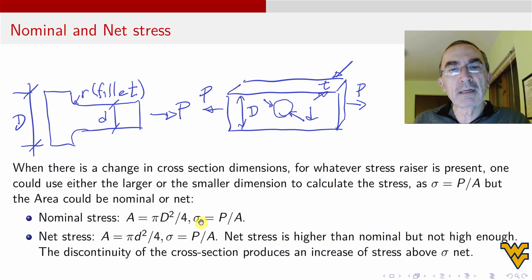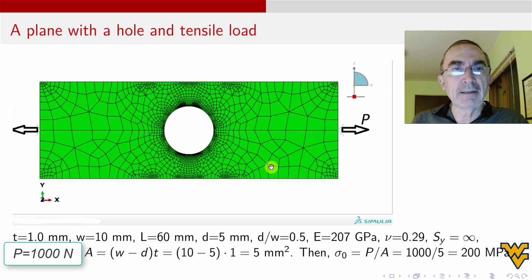The stress is calculated with mechanics of materials like these, and these are the stresses that are okay far from the discontinuity. This is the discontinuity, or the stress raiser. So let's say over here, yeah, it's okay. But for this part, no, it's not okay, because the perturbation caused by this region will extend to here and it will affect the calculation over here. Okay, so since calculations using mechanics of materials are simple, we want to figure out a way to extend this to calculation when we have practical mechanical components like these, with holes and with changing cross-section and things like that.